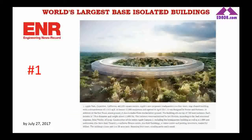And I will conclude with the world's largest base isolated buildings that was listed in Engineering News-Record magazine on July 27, 2017. The number one largest building is the new headquarters of Apple in Cupertino in California, covering 445,000 square meters, and it is the world's largest base isolated structure at the moment. And it's a prefabricated building. They constructed it very quickly. The prefabrication system is a very good match with seismic isolation. Since the displacements on the superstructure are very low, you can use prefabricated buildings easily without any problem and very quickly. So this is the largest base isolated building in the world as of 2017.